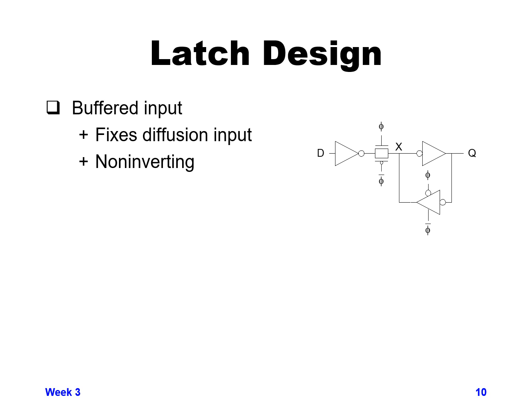And an additional thing that's not listed on this foil is you can see there's no backwriting issue anymore. Because when the latch opens, you have that inverter already built into this design, and you make sure that you will size that first input inverter to be large enough so that it will always be able to overcome that feedback tri-state. And so you have control of that in this cell itself, and make sure that you have everything sized correctly so that you won't backwrite and overwrite the value that you're trying to write in.